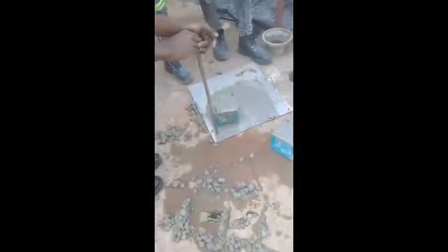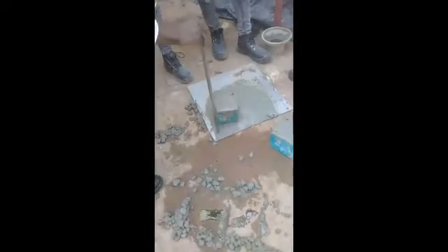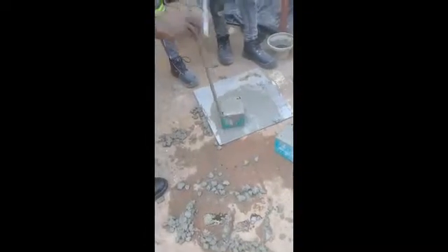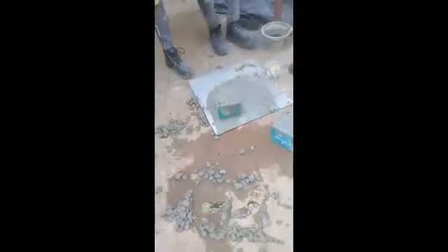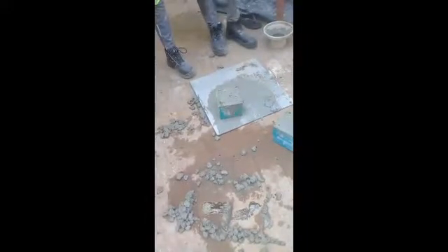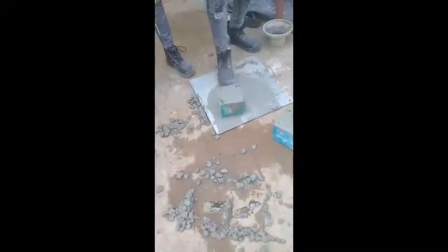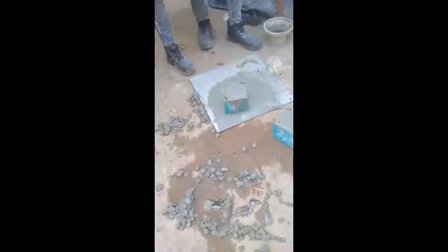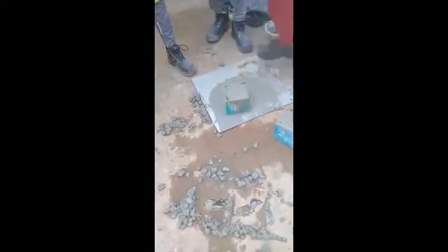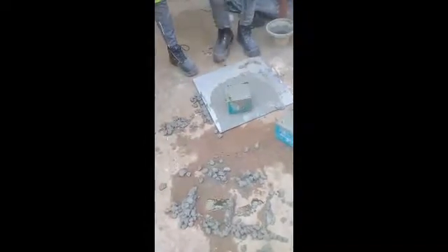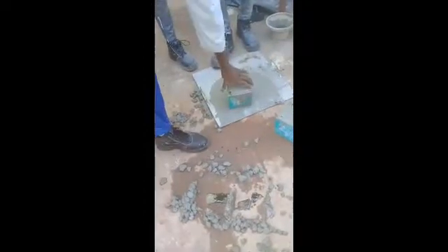After the concrete was compacted, the cubes were then given identities. They were numbered from 1 to 3 because there were three, and then they were placed in the lab to harden. After hardening, the cubes were placed in the curing bath for compressive strength purposes. The naming of cubes from 1 to 3 as a label helped the group because they were easily identified.